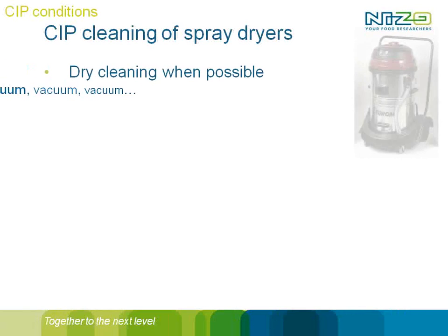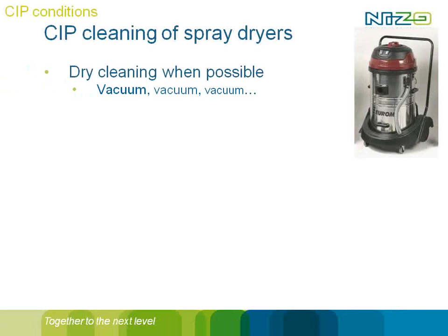Well, something to mention about spray dryers. Spray dryers are known. Okay, if you want to clean a spray dryer, I would say, well, don't. If you can have a dry cleaning, do it. And in that case, you should be able to vacuum, so remove the powder within your installation.